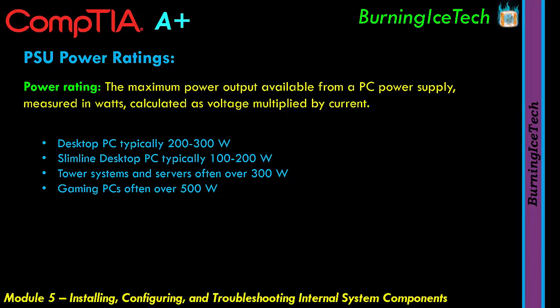So yeah, the average desktop PC I would say is about 350. I actually want to say 400 to 450 watts. Gaming power supplies will probably be about 500. That's still actually pretty accurate. So 500 and up, 500, 550, should be sufficient for a gaming rig. The bigger the graphics card, the more watts you want, and the more hard drives and fans you've got in your case. Also, if you've got a few fancy lights and stuff, then you might want to increase that to maybe 600, 650 watts or even more.